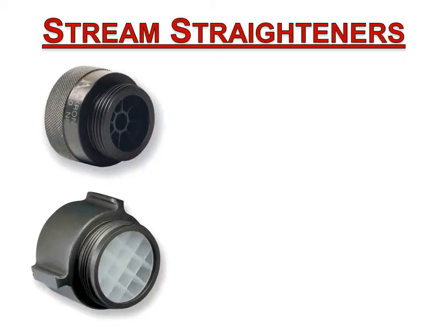Stream straighteners. Vanes set into the water stream reduce the swirling action of the water stream before entering the nozzle. Most of these you'll see on your master stream devices. There's usually a short piece, could be 6, 8, 12 inches long, that has the stream shaper in it, and the same way with some solid bore nozzles will have a stream shaper in them.